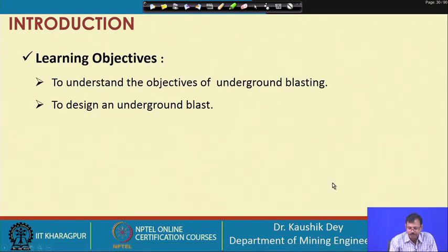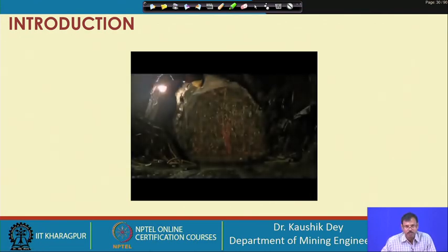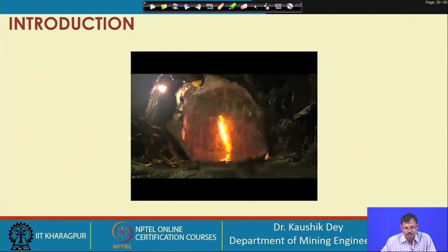Every class we start with videography. Let us see this video, which is also available on YouTube, of how underground blasting is in general carried out. Obviously, visibility is a little bit less. You can see this is the cut area, this is the tunnel area, and on the surface you can see the nonels available. The surface nonels are blasted, which are available on the free area.